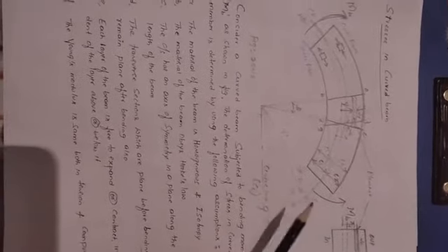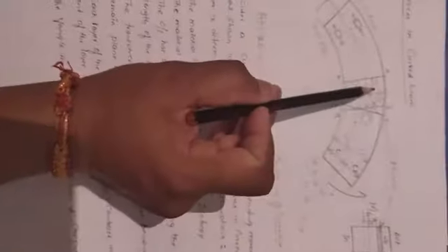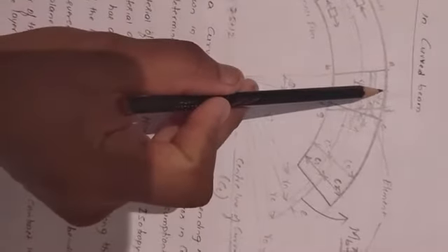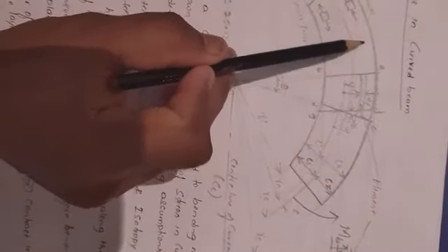And when a curved beam is subject to an external bending moment, how do the stresses occur? Here we consider a small element from the neutral axis in the positive y direction. It is subject to compressive stress, that is negative in nature. Consider only the right side portion with respect to AB. When the beam is subject to an external bending moment, what happens? The CD will slightly turn, meaning above the neutral axis the dimension decreases, below the neutral axis the dimension increases, so the change in the element takes place.